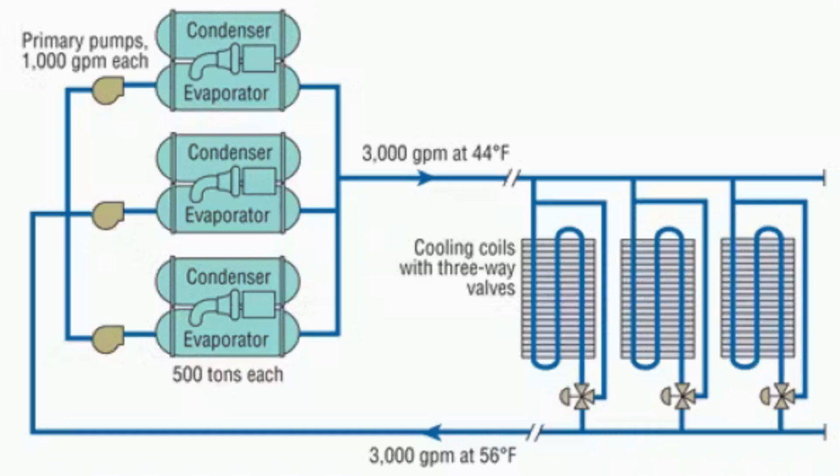Large systems, 6+ chillers or district cooling. Here, hydraulic balancing, power availability, and long piping runs become design challenges. Systems often use series counterflow chillers, manifolded pumps, and multiple cooling towers. Control systems may be PLC-based with redundancy. Even a 1% energy improvement can save thousands of dollars annually.